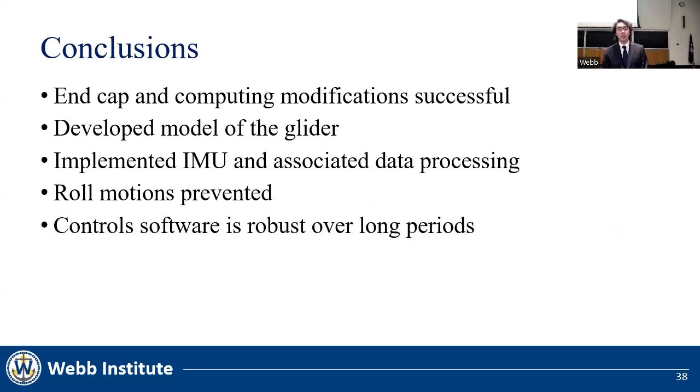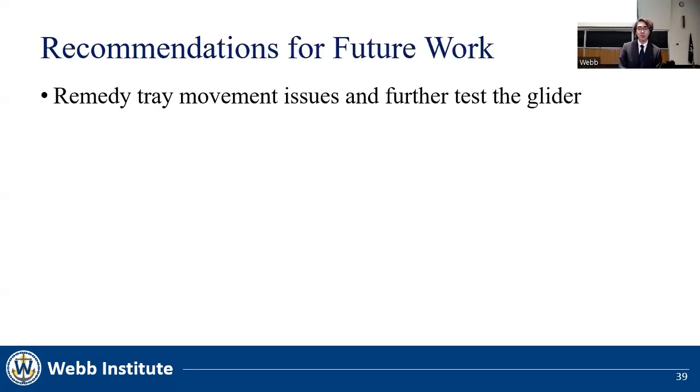The glider responded and performed test procedures as expected, even though the motor actuation was not enough to move the weight tray. The control logic for the PID control loop, as well as the overall system loop, proved to be robust enough to run, execute testing procedures, and record a comprehensive data log over the course of each testing period of over 45 minutes. We have a few recommendations for future work for students who are interested in working with AUVs.